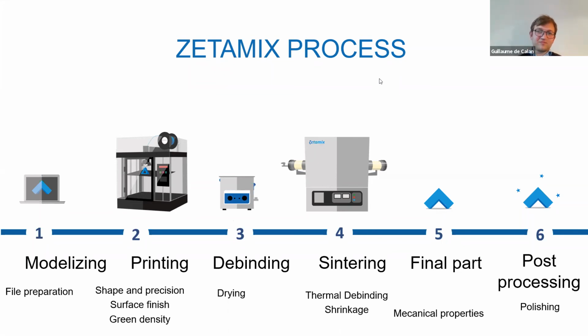Precision of plus minus 0.1, not micron, millimeter, I'm afraid, for objects up to 80 millimeters. It's not any shape, any infill combination. What I can tell you is if you're printing 100 millimeters and you want 0.1 millimeter precision, depending on the complexity of the shape, you may need to do at least one trial and error.